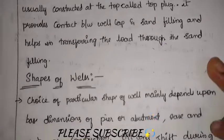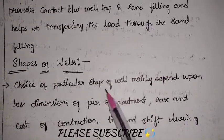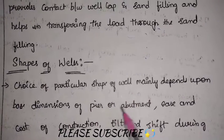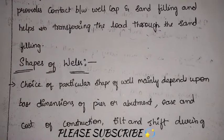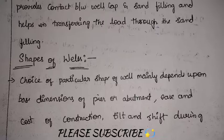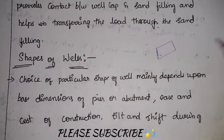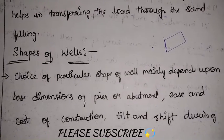Next, let us see what shapes of wells are generally adopted. The choice of a particular shape of well mainly depends upon the base dimensions of the pier or abutment. See, the foundation is below the pier or abutment. Whatever pillar is there, below that pillar we have this foundation. So depending upon the base dimensions, that is the bottom dimensions of the pier or abutment, we will choose the shape of this well.